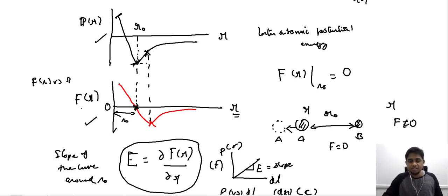And besides that, it is also possible for us to say that when we are comparing two different metals, the one with the lowest interatomic potential in the stable state, when compared to the other, will demand more load to bring about an elastic deformation when compared to the other with the higher interatomic potential. Even that understanding can be gained from the discussion from the atomistic perspective.